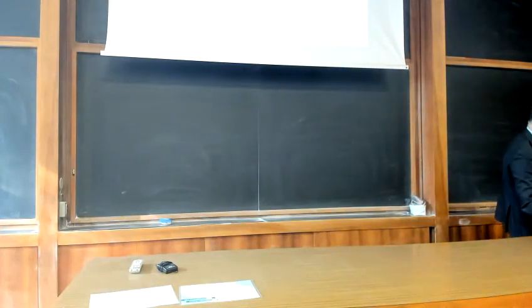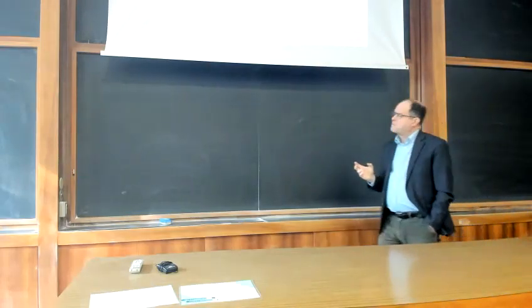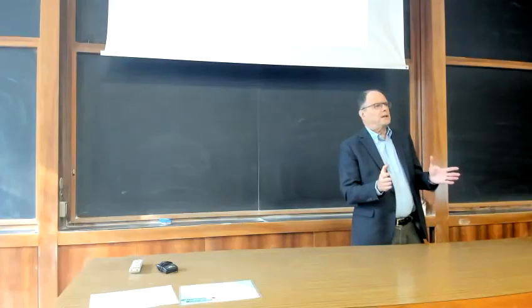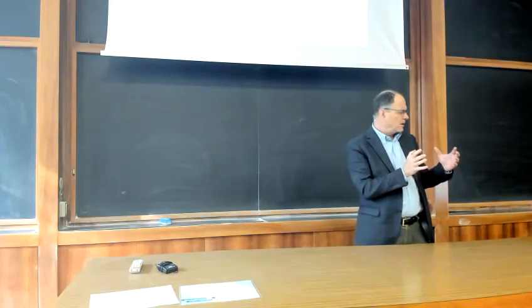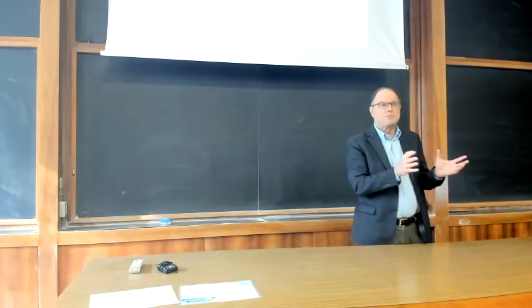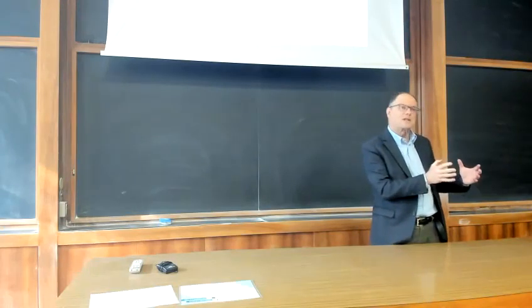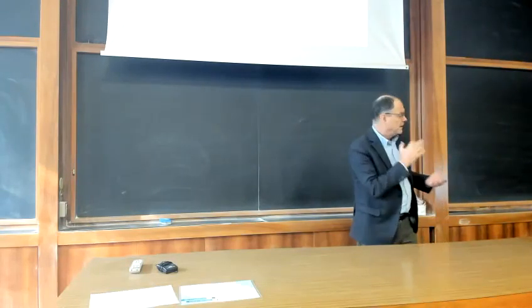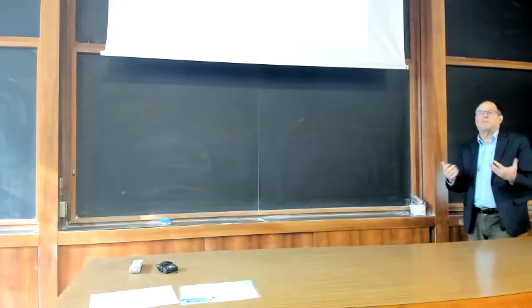But the definition of such a limit load is not uniquely determined. It's a bit awkward, because you define a maximum limit load, a bearing limit, by defining a maximum settlement. So you define a maximum load, but you have to define a maximum settlement in terms of deformation. We have no alternative, because this is what happens